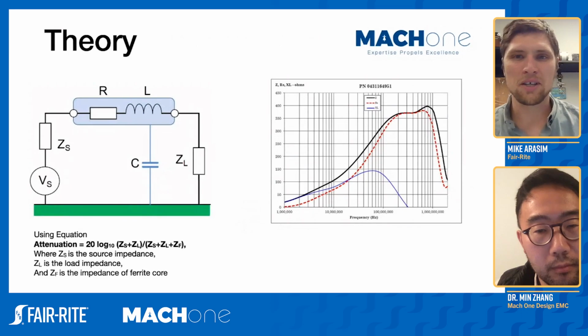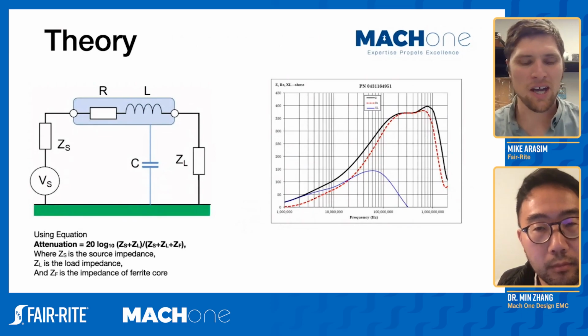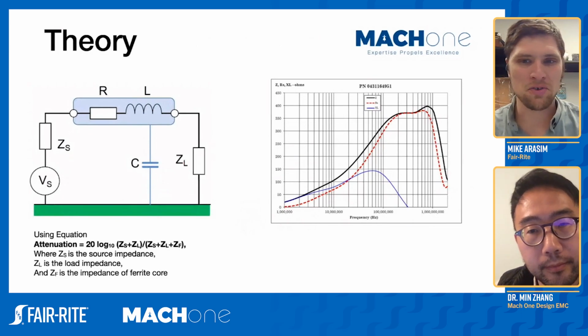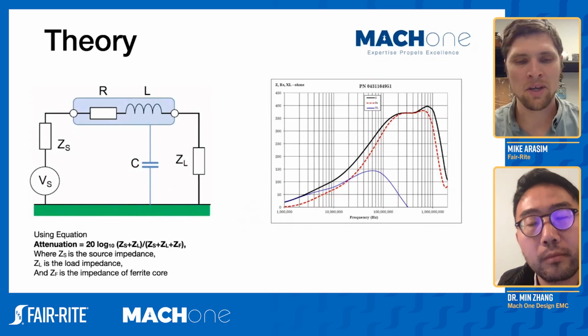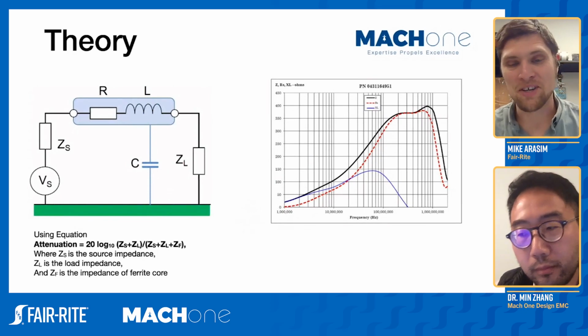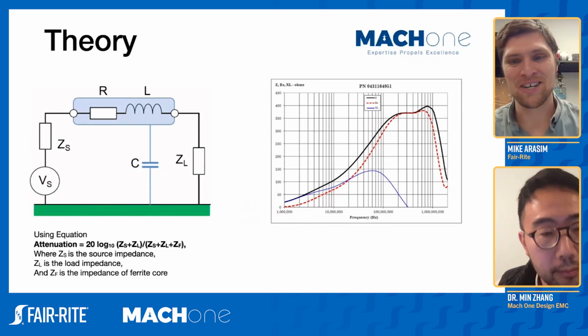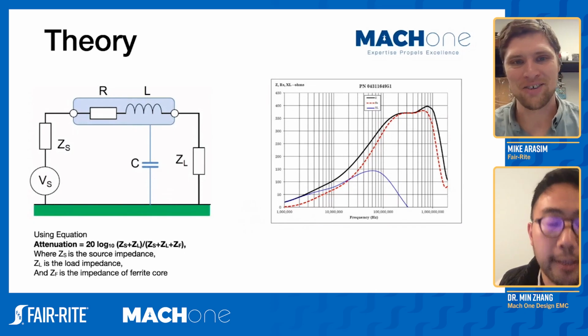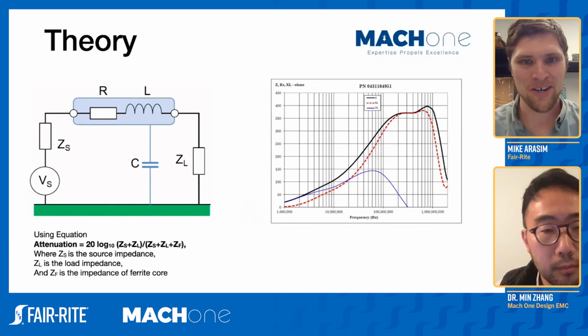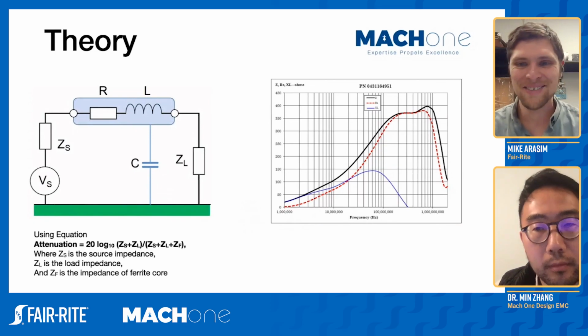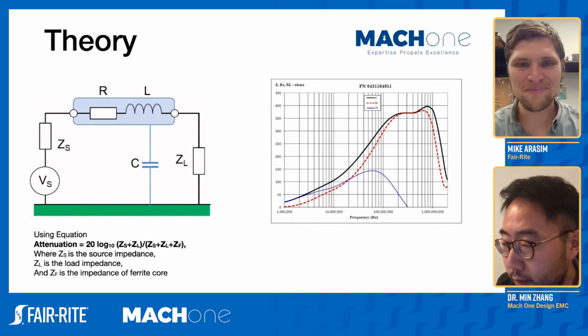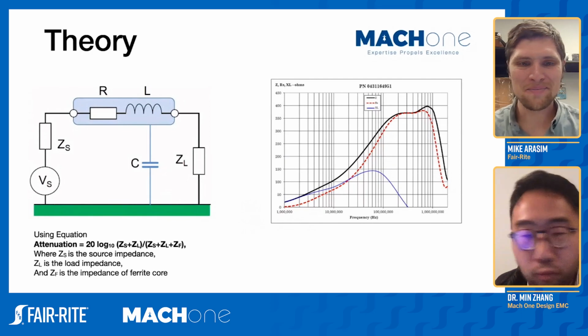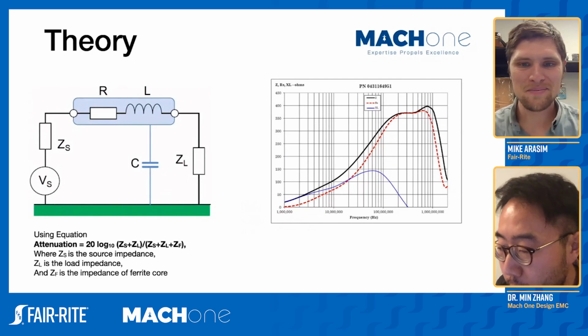You do at times by way of caring about that absolute impedance. Typically, there's not going to be too many applications where you're deliberately designing to have a high reactance with a ferrite. Well, speaking of suppression applications, now if you're trying to make something like an inductor or transformer, you absolutely want that high reactance, and ideally you want the losses there as low as you can get them. Okay, so that's about the theory of a ferrite core.